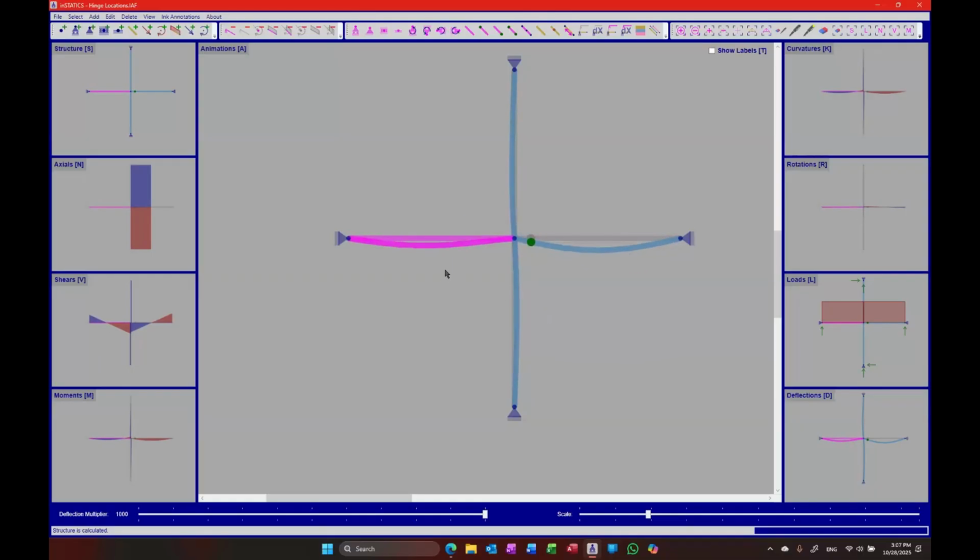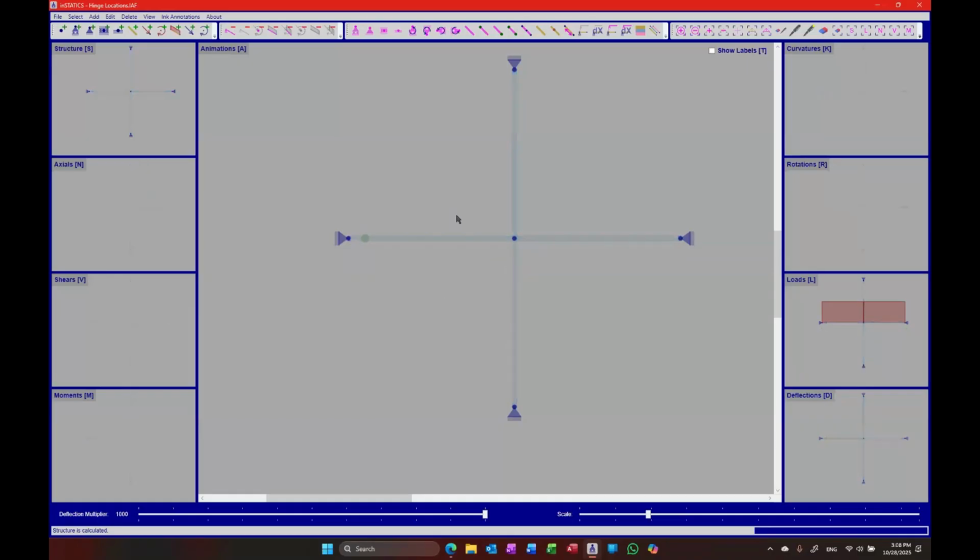While if I have the hinges at the ends, I can control where the moment shall flow. So independently, I can decide which one of these elements will be fixed connected to the column and which one of these will be simply connected, right? And you can't really do that if you make the joint itself hinge.